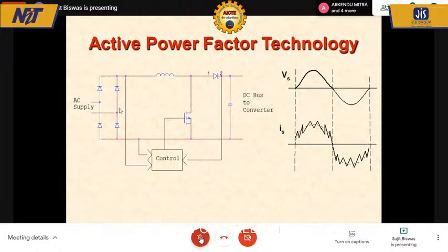So the expression is E equals L di by dt, and the current starts rising through the inductor. I monitor the current and switch it off immediately, so that energy has been built up in the inductor. When I switch it off, the energy will keep flowing out. As per Lenz's law, in order to maintain the current flowing from left to right, the right hand side becomes positive in polarity of voltage. So the voltage across the inductor gets added to that of the supply. The voltage is sufficiently large to send energy out into the output side, the right hand side.